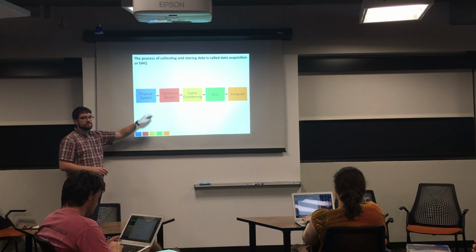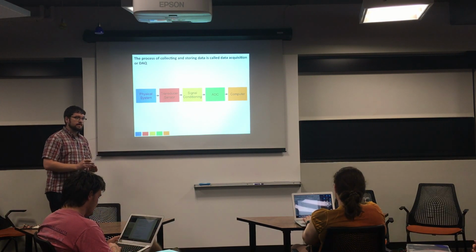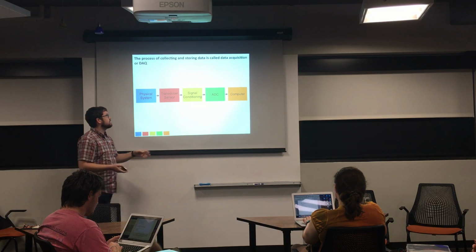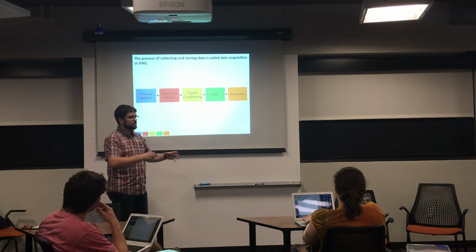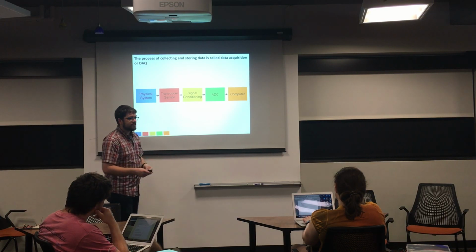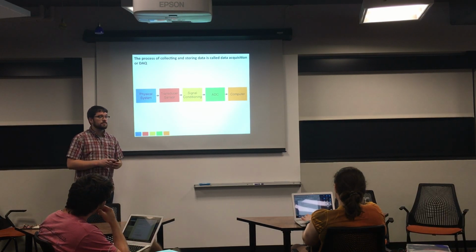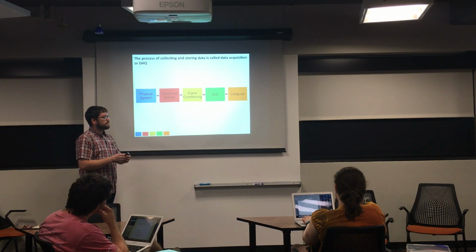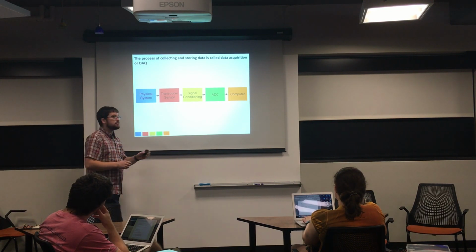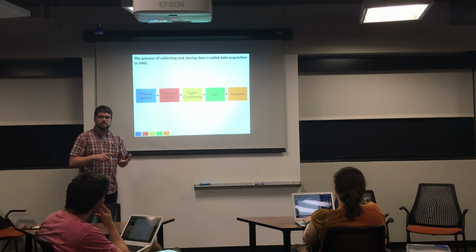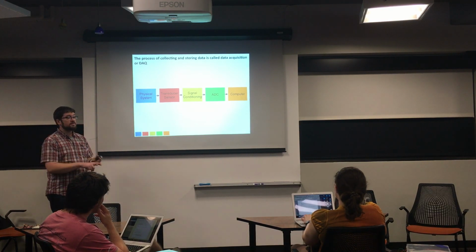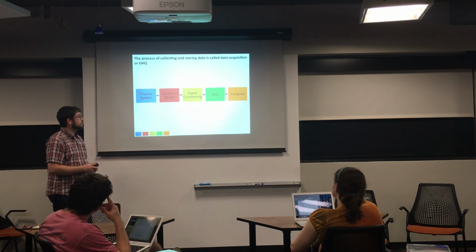So first you have the physical system, which is what we actually care about generally, and what we want to sense. You get your transducer or sensor to actually turn the physical system into some kind of electrical signal, but generally that signal isn't good enough on its own. Especially in geoscience, we're measuring very small signals, so you have to have some kind of signal conditioning, where you generally do things like amplify the signal, or buffer the signal, or maybe even filter the signal to get some noise out of the signal that you don't care about.